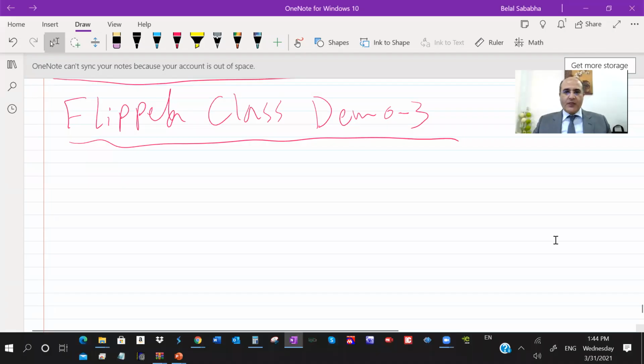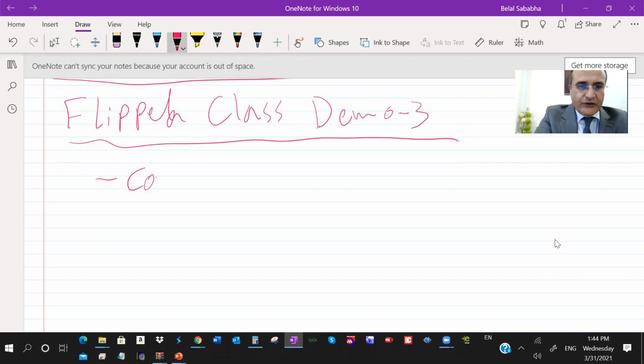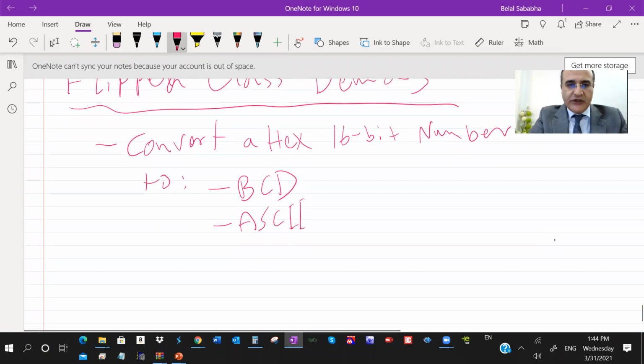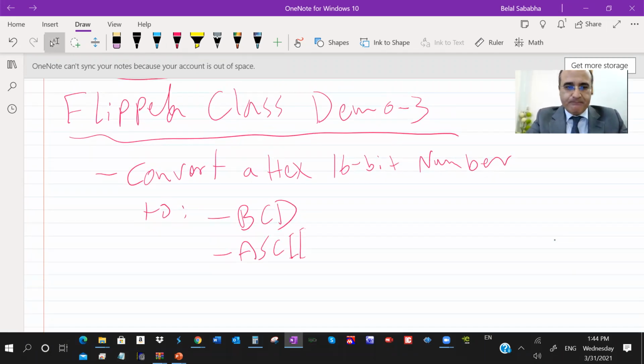In this meeting, I'm going to write with you some code to convert a hex 16-bit number to first BCD, binary coded decimal, and ASCII, the ASCII code for each decimal number that we get in the BCD.